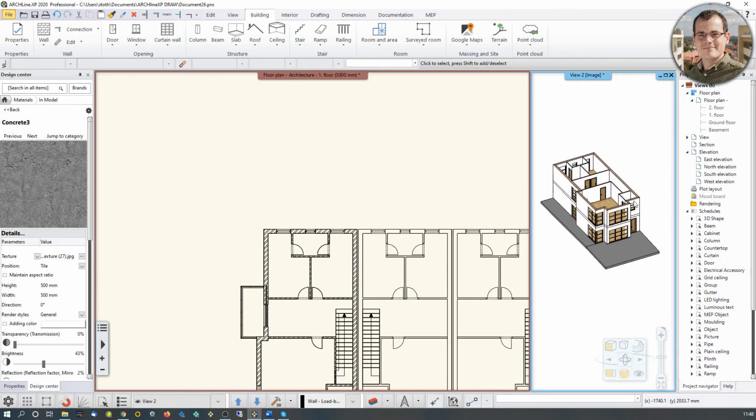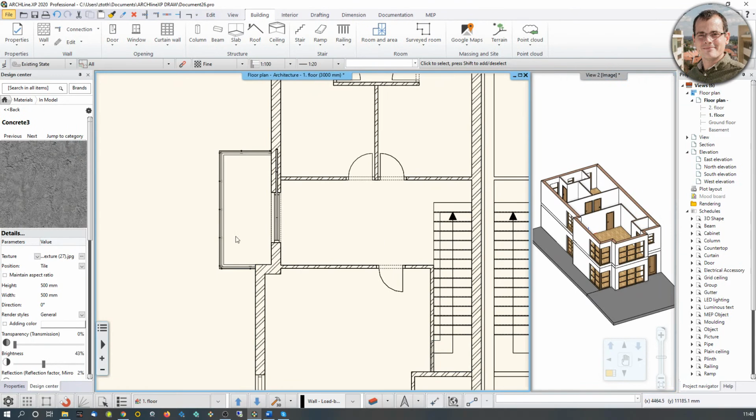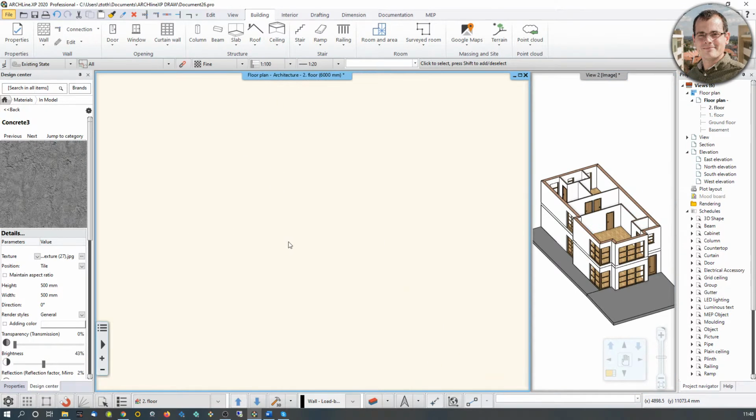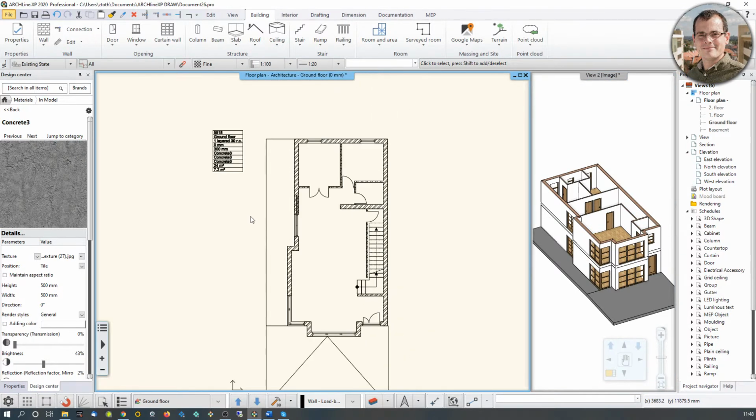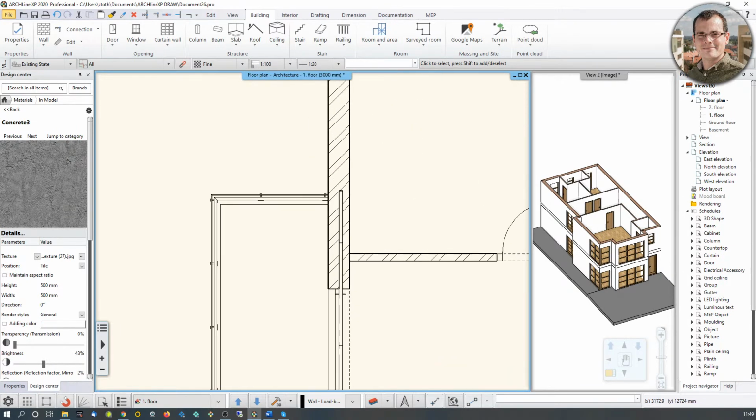Okay, so nice, I actually have 2 floors. But a couple of things are still missing. And those things are the balconies and the railings. So that's what I'm going to look at next. For the balcony, I'm going to use the Slab tool, just like I did before. I'm just going to make sure with the Page Up and Page Down buttons that I'm actually on the right floor. So this is the ground floor, this is the first floor. So this is what I have to retrace.